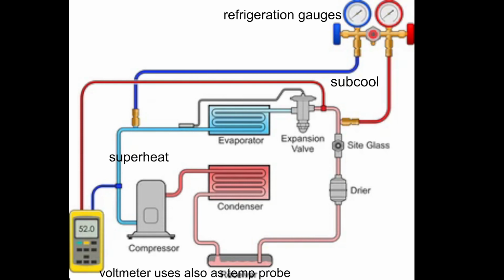It has a temperature probe setting on there where you can get a clamp to clamp onto your suction side. As you see, it comes off the meter and it's making a temperature reading. The other one, if you want, you can run oppositely off of that one and go over to your high side. So if you're doing readings on the cool side and you're charging it, that's called superheat. If you're charging it and on the high side, it's called subcool.